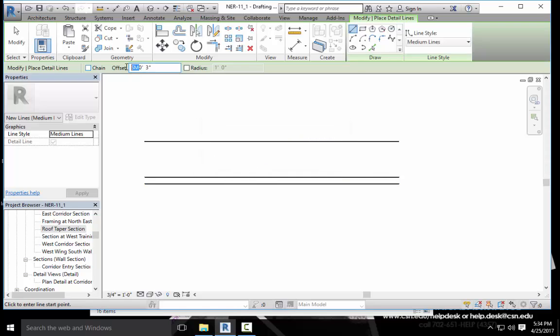I put an SM up here. I didn't want to do that. Alright, we're going to draw that down for approximately 1 foot 9 inches. And I could drag this out, or I could just type 1 foot 9, which would be easier.